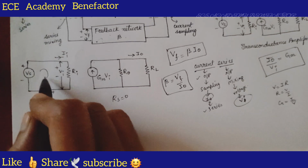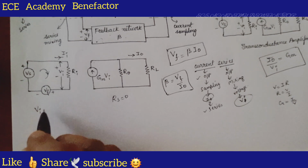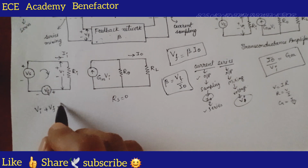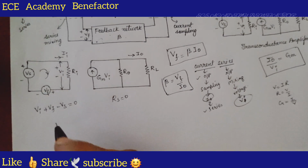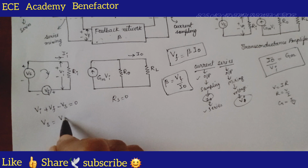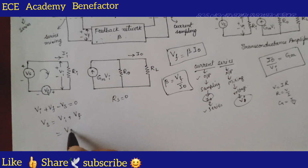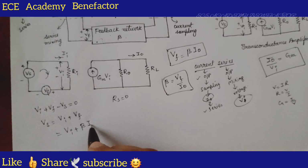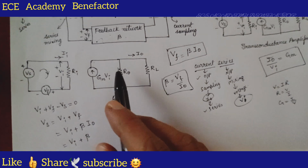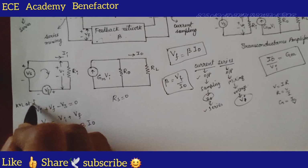Now write KVL at the input side. Apply KVL to the input loop. We are entering at the plus of Vi, Vi plus Vf, entering at the plus of Vf, and entering at the minus of Vs, is equal to 0. So what is Vs equal to? Vs is equal to Vi plus Vf. And what is Vf equal to? Beta times I0. What is I0? Now apply the KCL. This is KVL at input.